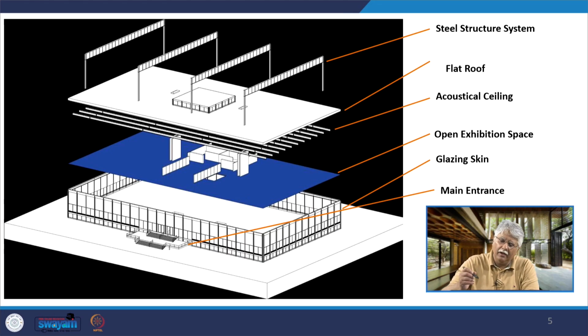The parts are independent of each other, and they come together to form one building. One is of course the steel frame, the structural frame, which is the columns which we see on the outside of the building, and the inverted beam or girder at the top, so that on the inside there is no beam.